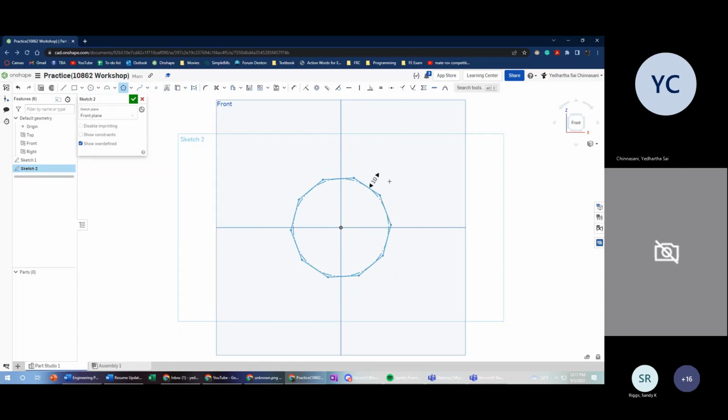We use this a lot to make our axles, our 8mm REX axles. Everything else here is basic. Point: if you want to create a point in floating space, this is what you use. And then construction lines. I'll get to construction lines a little bit later because I use them a lot, but I won't explain them without any references.